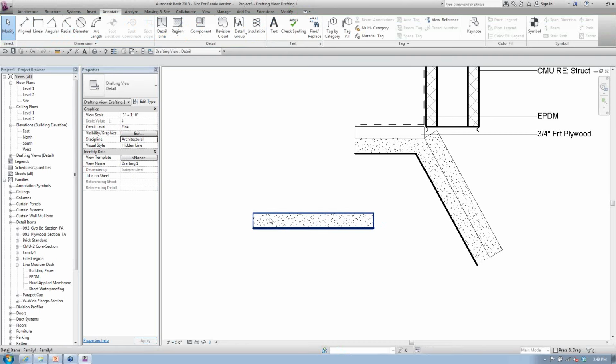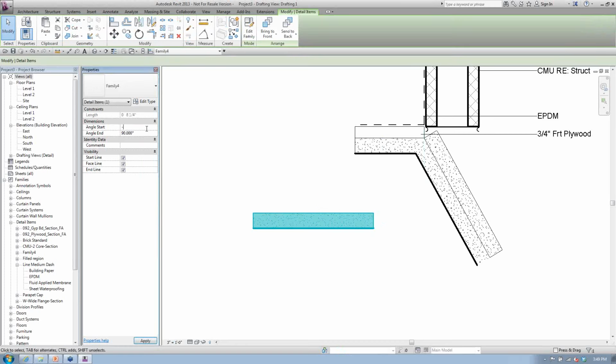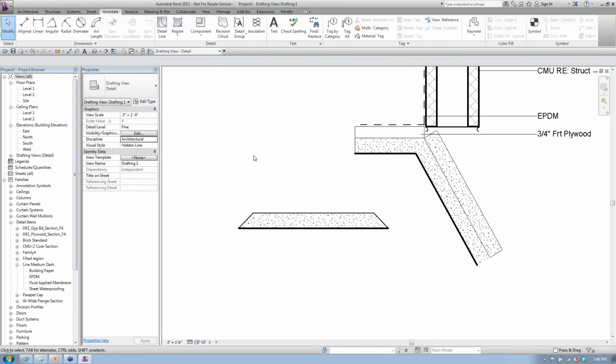What's great about angle values in Revit is you can also make it like a -45 to go the other direction. Make this one a 45. It looks like everything's working for me. So I always test these in a sample file just to make sure it's working. And I always like to tell people, make sure that sample file is your company template. I've actually seen families work fine in the out-of-the-box, but it doesn't work in the company template.